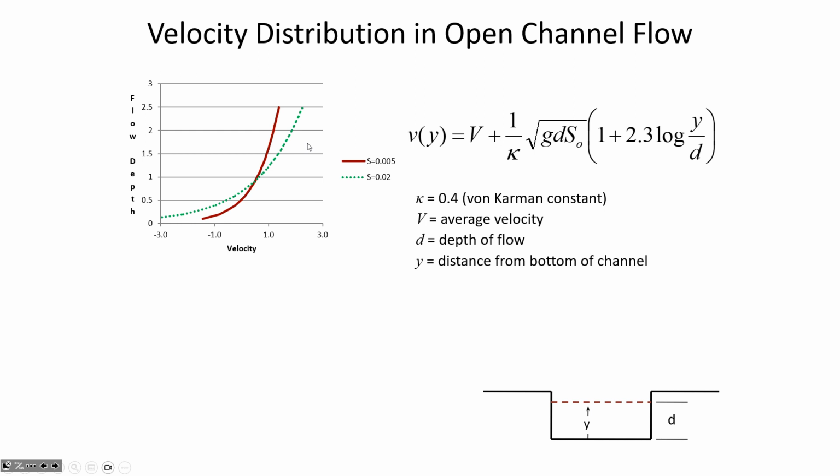When you get really close to the bottom of the channel, this equation isn't really effective at reaching that 0 point. You see how it's actually predicting a negative velocity once you get into the really shallow range. So you'd need to override this equation at the end and just note that it eventually reaches 0 and it's not going to go into a negative flow velocity.